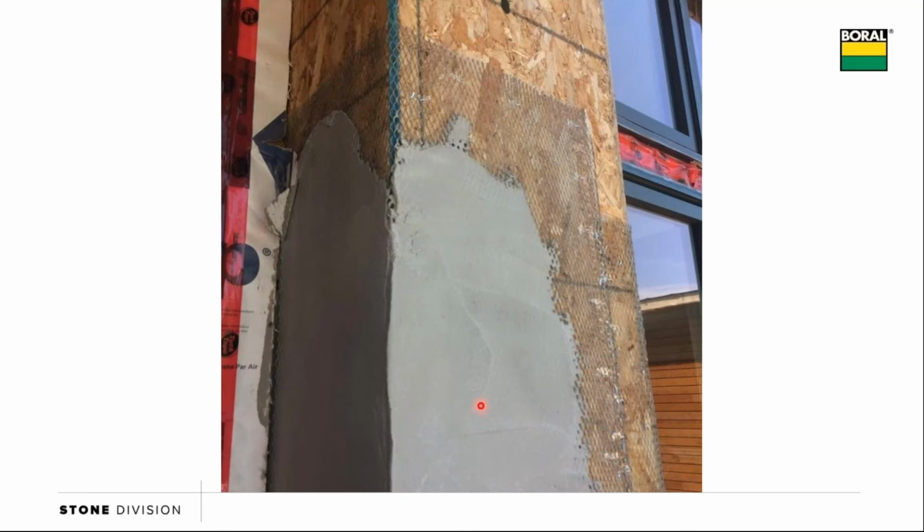So if you said the scratch coat, maybe a hair thin, but definitely doesn't have any horizontal lines in it, you'd be correct. If you said the metal lath is standing straight up and down, you'd be correct with that. That's improper. You can see almost a gap in between this transition between the two. So what's keeping water from getting in there? We've got a flashing issue at this point. Well done. If you said we're missing 2 layers of paper, I will give you a gold star by your name. Well done for today.